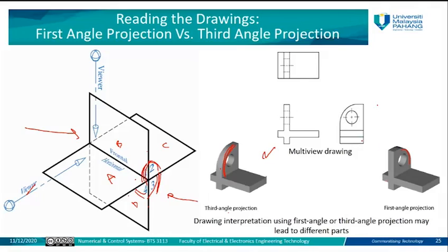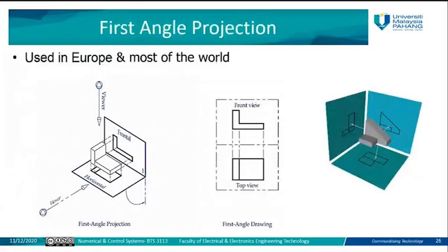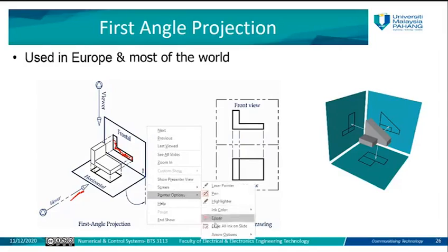We will see here how the first angle projection looks. You come from this side, from angle number one, and you want to geometrically project this product onto this side. So how do we represent this product on the front side? It becomes represented like this. This is the representation of how you are going to see this product from this side, with angle number one, the front side angle.